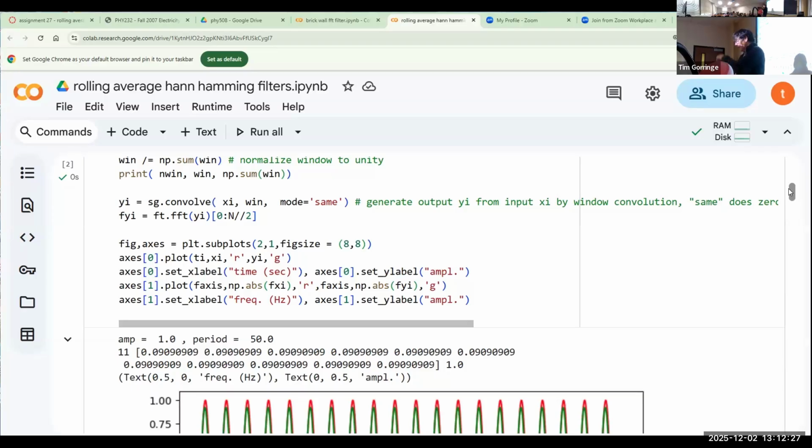One thing you can do is just pad the input with extra zeros so that the convolution still works on the first sample, second sample, third sample. It's just convolving with a padding of zeros. And that's what this same argument does. When you pad the ends of the input with extra samples so that you can carry out the same weighting over the full range of your input samples, that will give you an output that has the same size as the input.